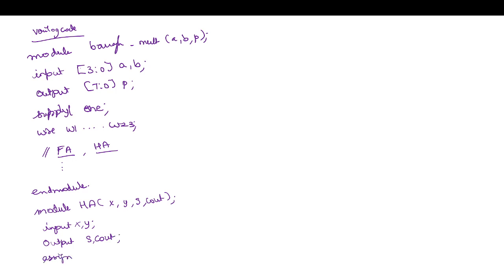Assign S is equal to X XOR Y, assign C out X AND Y. And then end module.